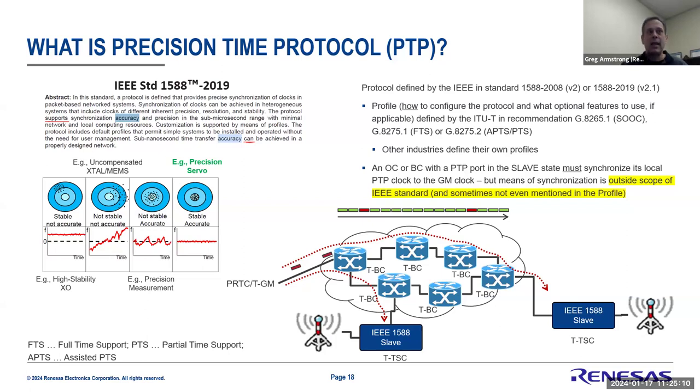But it is able to maybe clock something very accurately. That could be an example of these high stability oscillators. You hear about high stability TCXOs or high stability OCXOs, where if you measure the variation of that clock over time, it's very stable. You get a very stable error, and that error is bounded so that you almost get a flat line when you look at it from a phase and time relationship.